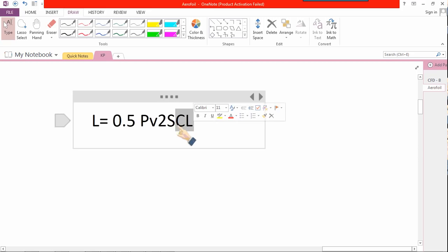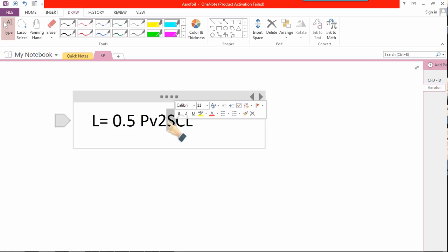So I need to measure the area in the local flow direction. The aerofoil will have some surface area on the top and bottom. When it is projected on the flow direction, what is the area? That is where the flow is going to be attached. So this is the wetted surface area.